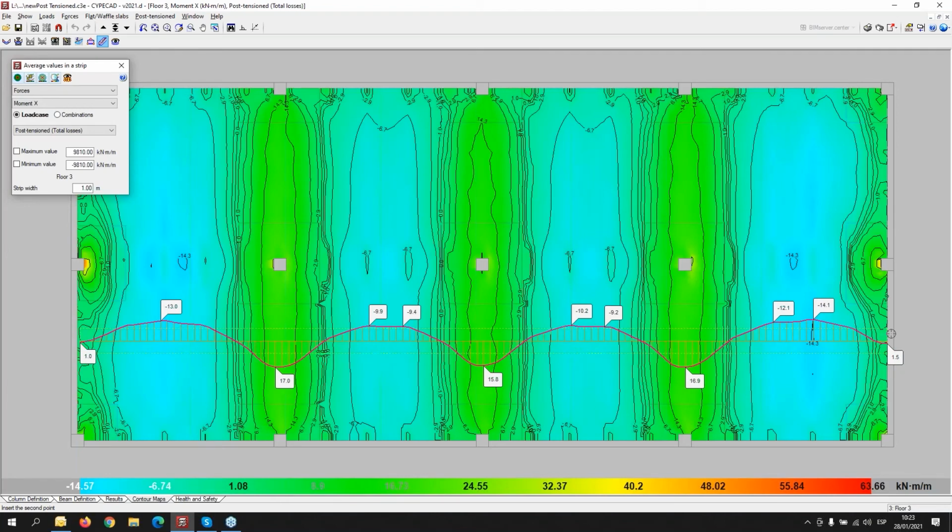Okay. It may be interesting in this case to compare the stress and the forces applied by the self-weight and the stress in order to apply a criteria to, for example, have an order of how much of the self-weight of the slab may be equilibrated by the forces applied by the post-tensioned elements.